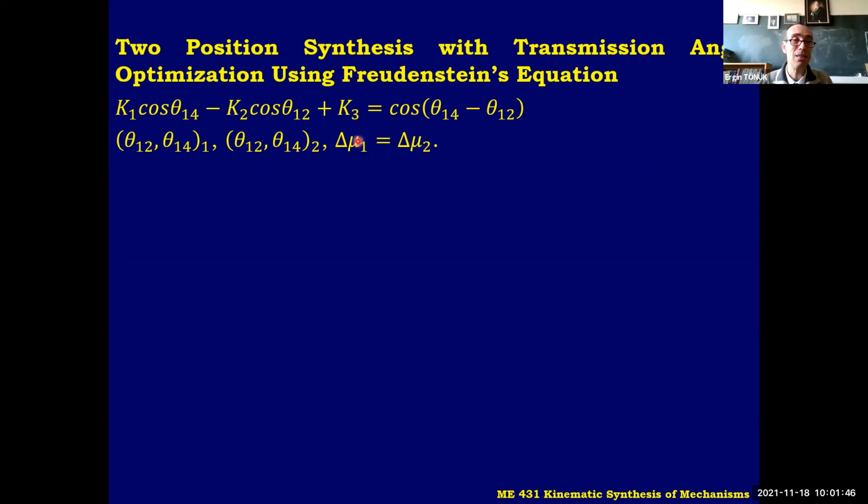If the two deviations are equal, and if they are acceptable, like this is 35 degrees or so, so is this, that's very good, okay? But this does not mean that it is the best solution. You can't obtain something smaller than this. So in using this word optimization, we should be a little cautious, okay? It's not the absolute minimum. It doesn't mean that it's the best value. It means only the two deviations are equal, okay? So we can use this as well.